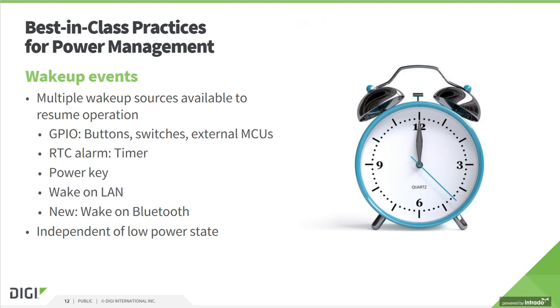Another very common option is to use the real-time clock simulating a timer. If the system offers one or more tampering pins, which are normally used to detect external unauthorized intrusion into the system, for example, an attacker trying to open the enclosure, this can be used as a wake-up source as well, to allow the system to react to a security breach, even while being in a low power state.